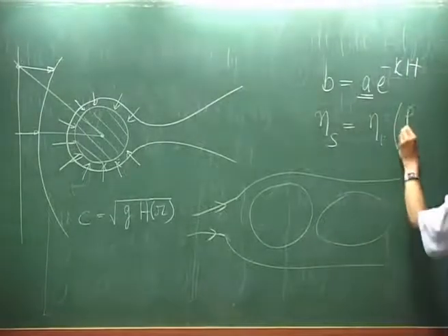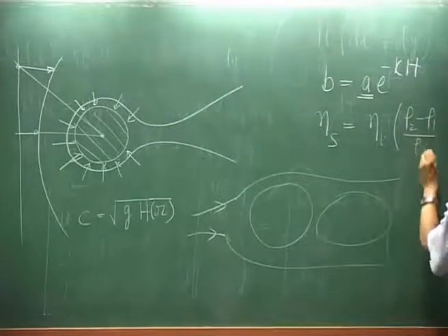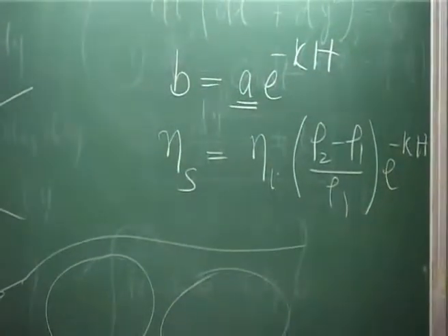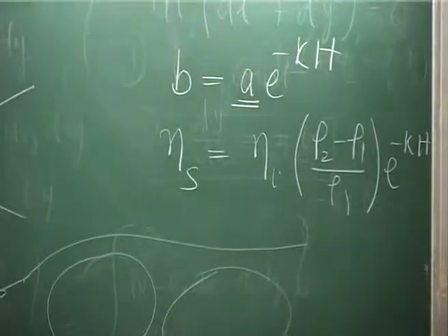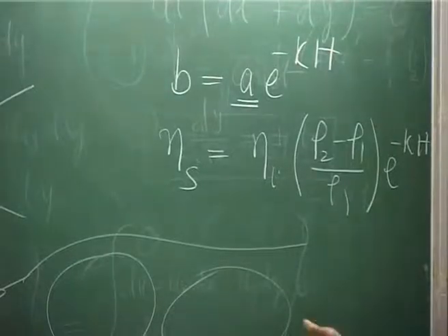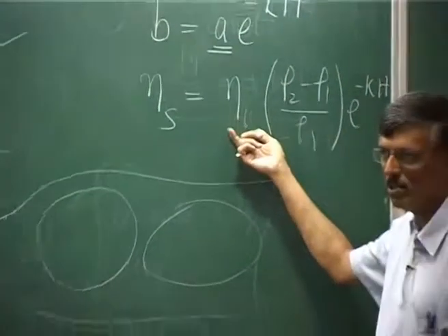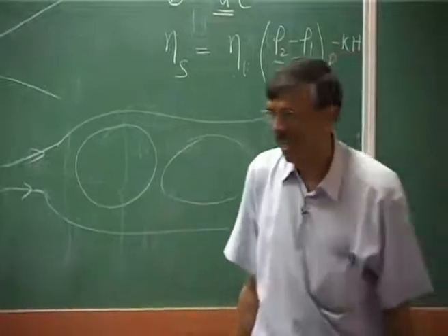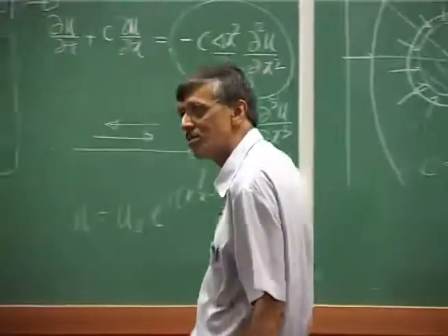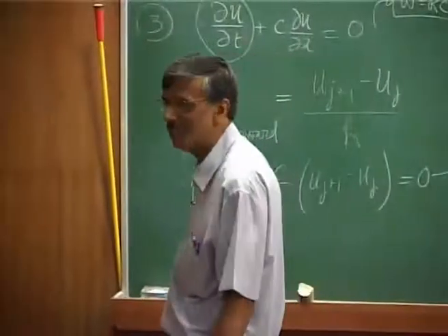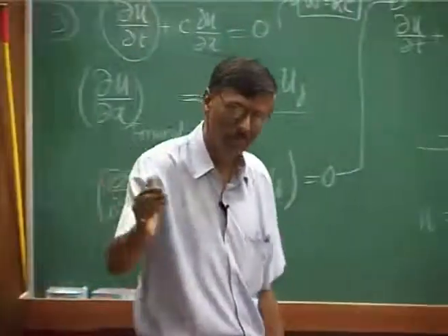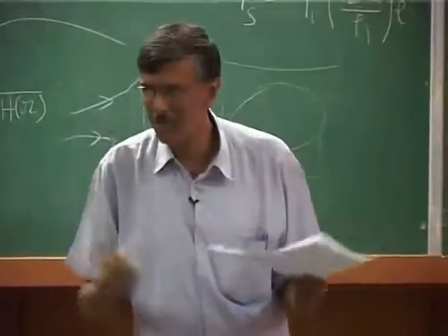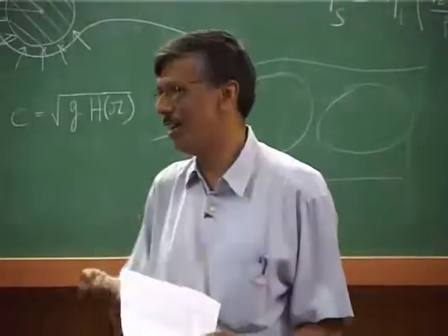There would be, I do not remember the formula, but it should be something like this. Okay. If you look at this, then what you find is a very, very interesting thing: the internal wave amplitude is going to be very, very large compared to the surface wave. In fact, this was a kind of a mystery to all these people entering the harbor. They always used to find that as they come to the port through the estuary, all of a sudden they experience very large drag. Why?